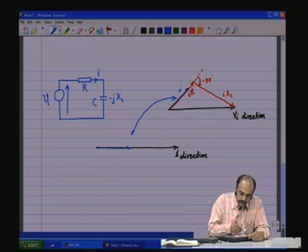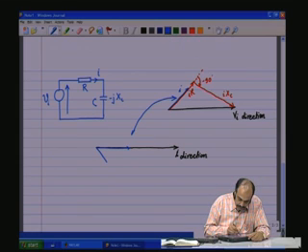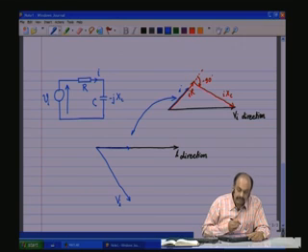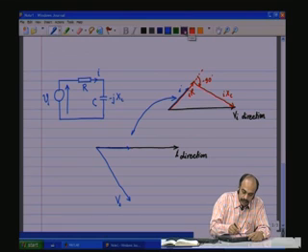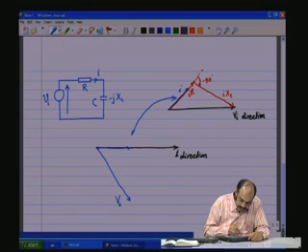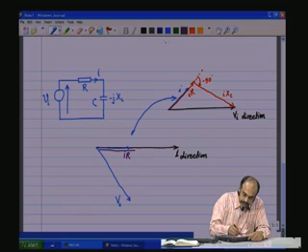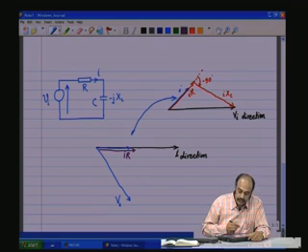Therefore, the input voltage is lagging the I. So, I have the input voltage which is lagging the I, this is going to be VI, and that is formed by I into R, this is the vector in phase with the I, and then I into minus j XC, minus j means minus 90 degrees rotation.